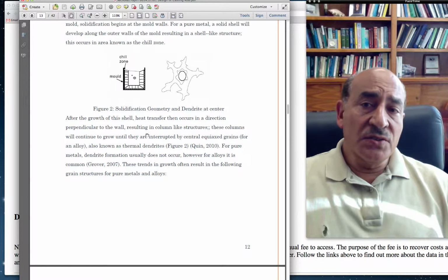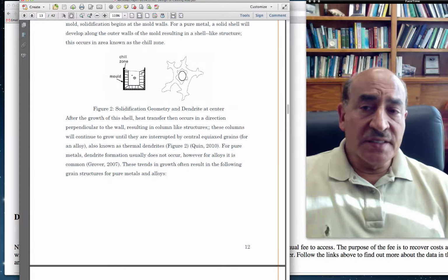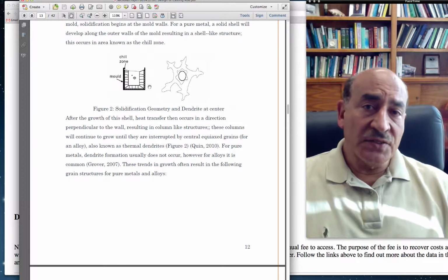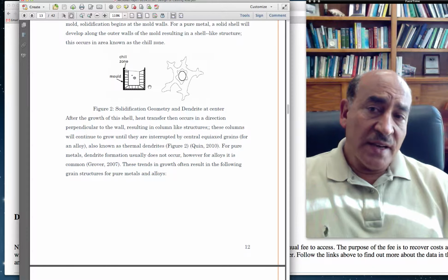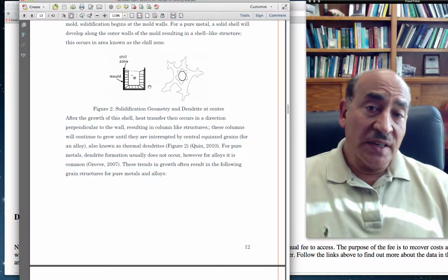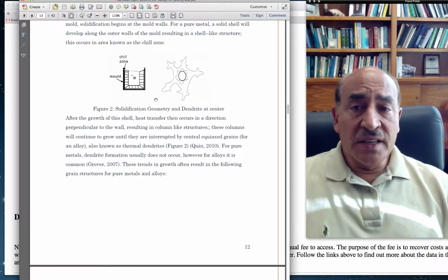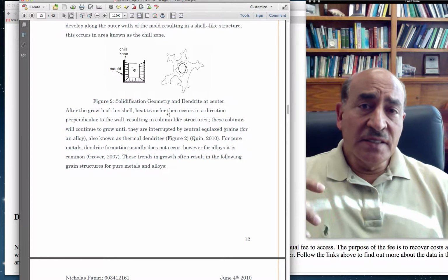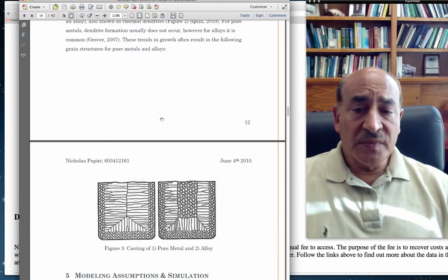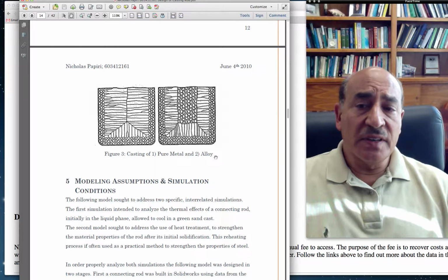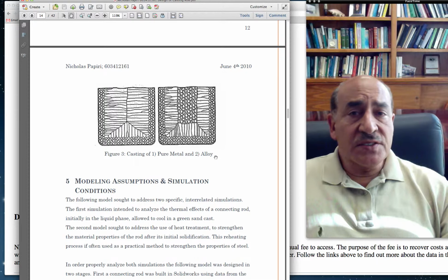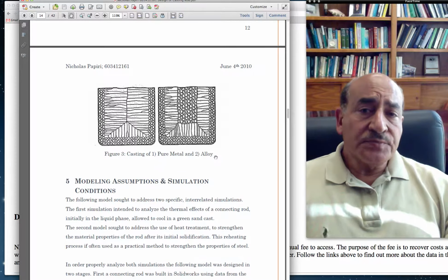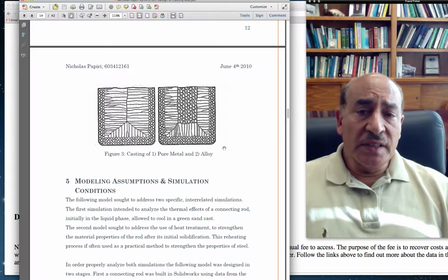And then he goes into the real problems in casting, where you have grain: the solidification starts from the outside of the mold, and then the grain size changes as it gets cooler, and the grains will change until you get to the core, and what happens to the grain size, and how you can control it, and so forth. And here's an example where you can have quite inhomogeneous material, because the strength of the material depends on how you control the grain size and how you can have it more uniform if you want.